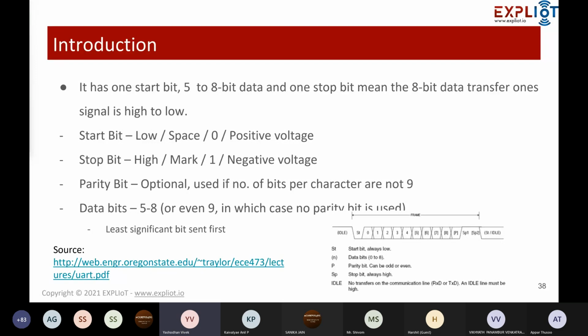For that, what we do is have a start bit, and we send 8 bits of data, or whatever the format you have, 5 bits, 8 bits, whatever format. And then after that 8 bits of data, again you send a stop bit. So this is the standard format UART follows. Again, for error detection, we can use the parity bit, having even or odd parity, right? So this way the frame is basically getting communicated.